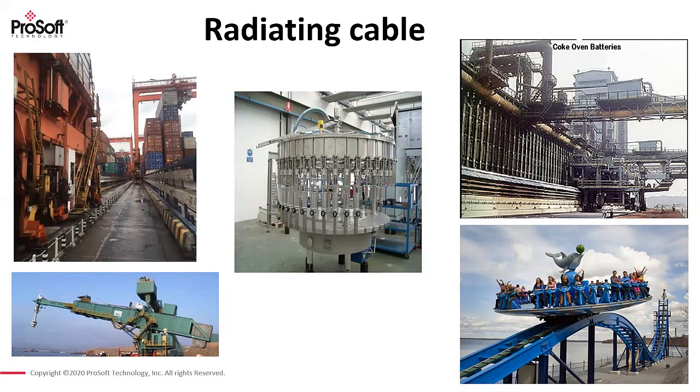In the middle, we've got a bottling machine. So with this bottling machine, it fills bottles, about 5 bottles a second. Previously, this was using slip ring technology. Now we've replaced the slip ring because you have wear and tear issues. And we do this with Wi-Fi using leaky feeder cable.